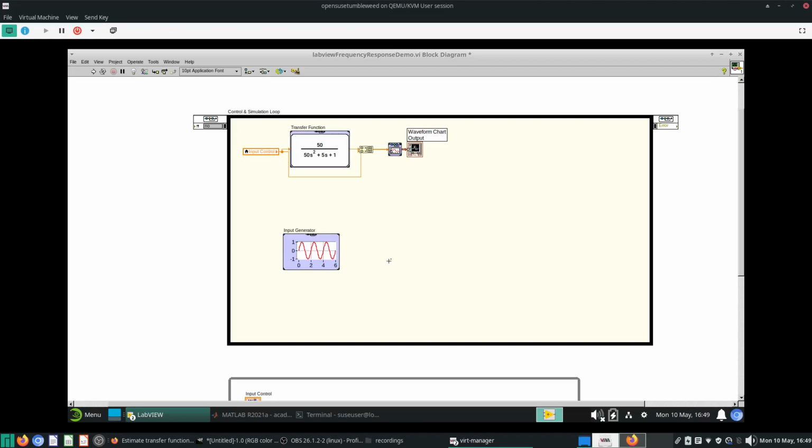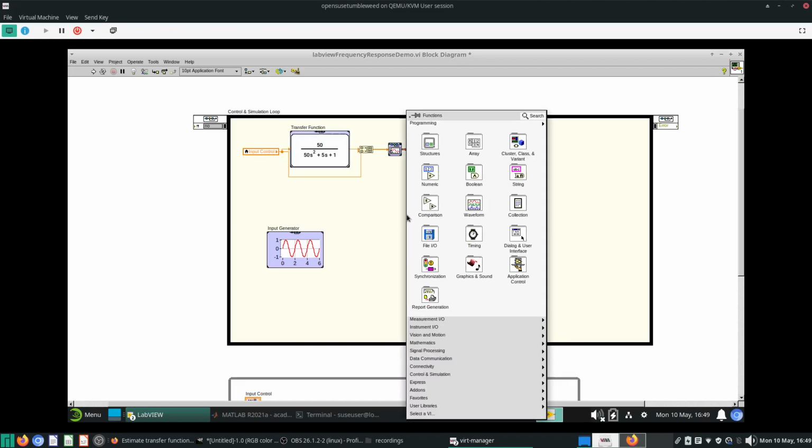Classically we like to use sine waves. Sometimes we can use square waves or even sawtooth, if we want to spread out our analysis over several frequencies and get more data points per test, because those are superpositions of many sine waves. Of course, for nonlinear systems that might not always work. For a linear system it's pretty easy to do this. So next thing I want to do is to start making a nonlinear system.